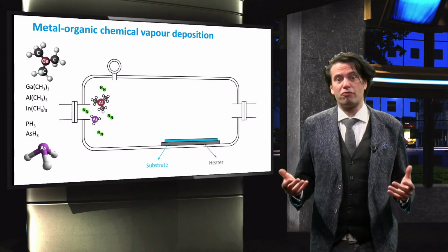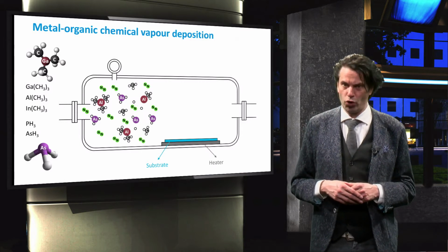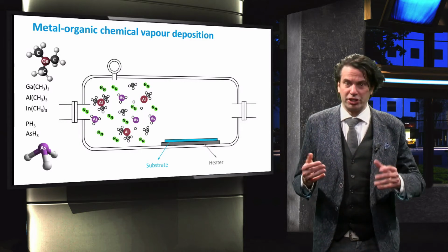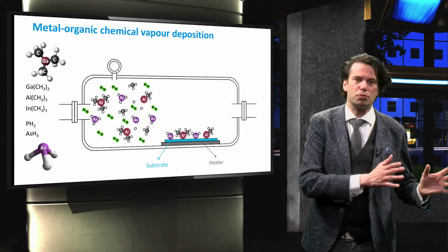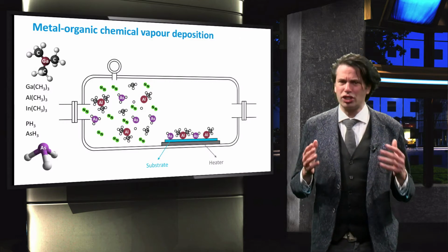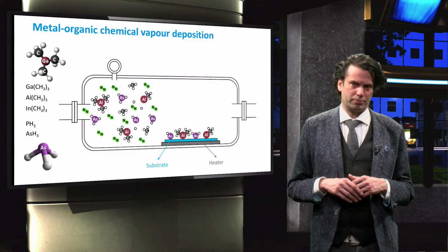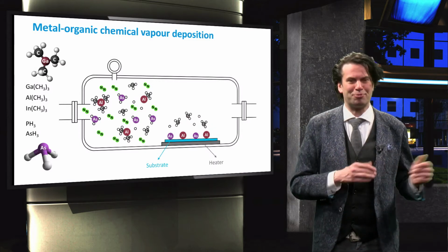Thermal energy coming from the heater partially dissociates the precursor gas in the gas flow. Intact and partially dissociated gallium and arsenic particles alike diffuse to the substrate surface. The high substrate temperature causes the gas particles to further dissociate, so that mostly pure gallium arsenide is grown.